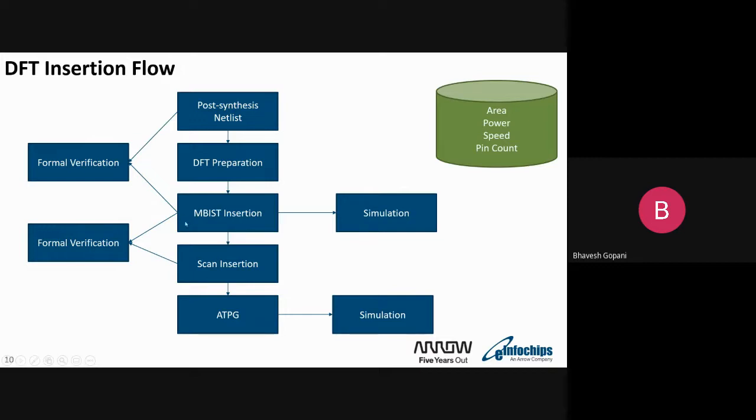So this is a very important stage also. Here we need to check because once we are optimizing and inserting some logic in the actual synthesis netlist, it should be logically equivalent. So if something is missing, we can easily identify or catch it here in the formal verification stage.